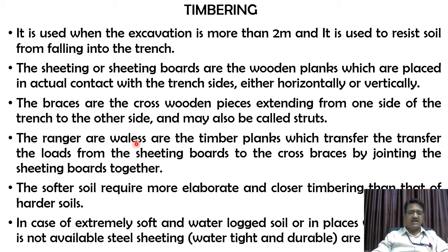The rangers or wallers are the timber planks which transfer the loads from the sheeting boards to the cross braces by jointing the sheeting boards together. So rangers or wallers are the intermediate sections that transfer the load from one component to another one.